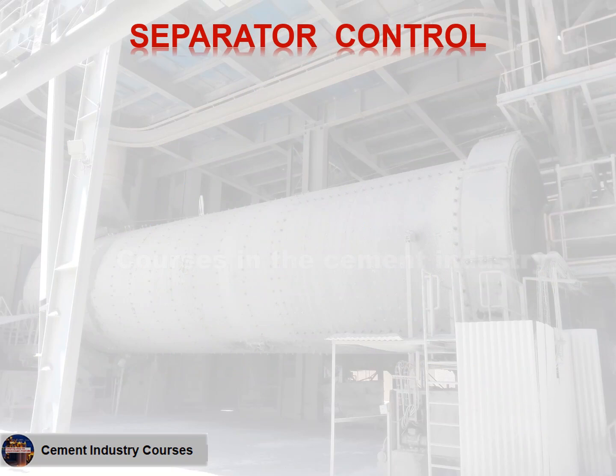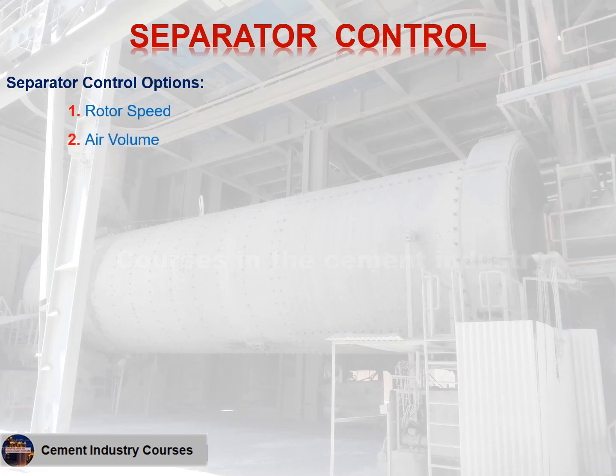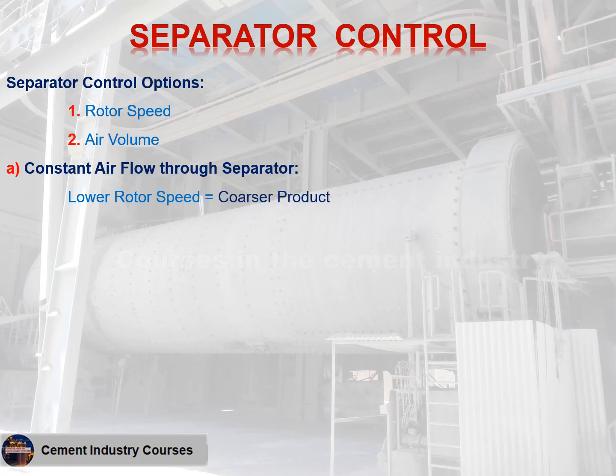Separator control. Separator control options: 1. Rotor speed. 2. Air volume. A. Constant air flow through separator. Lower rotor speed equals coarser product. Higher rotor speed equals finer product.